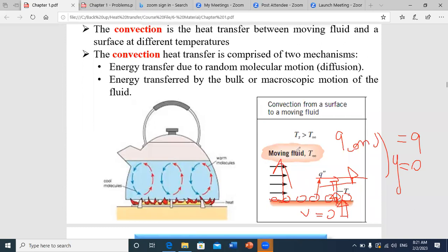Sometimes we'll see in the course that you can have heat loss by both convection and radiation. Then you should sum the two fluxes. But here we are just considering heat loss by convection. So you say that Q conducted through the air molecules at y equals 0 is Q convected by air. And this will be the equation governing cooling of your surface. Okay.